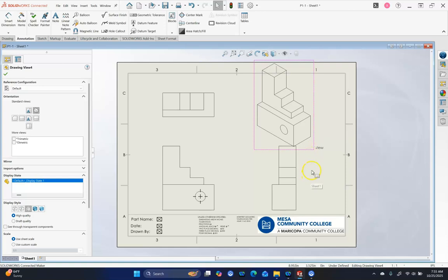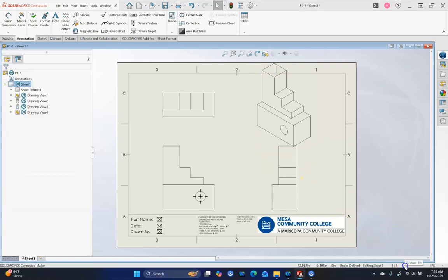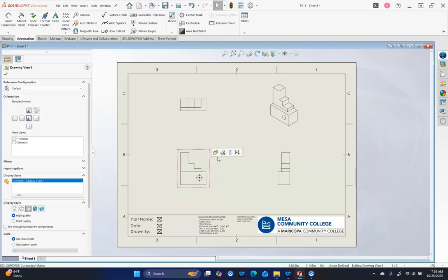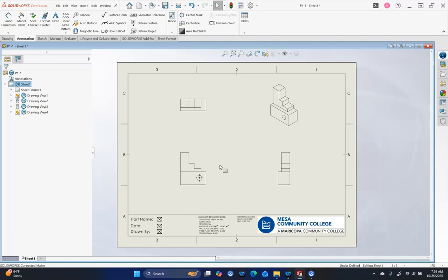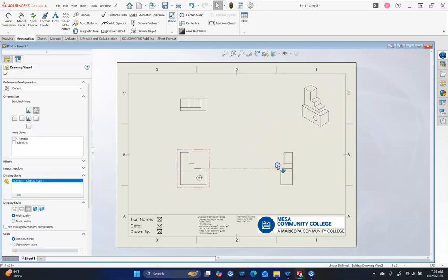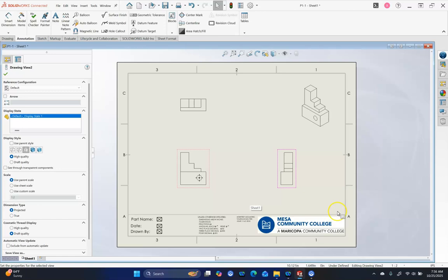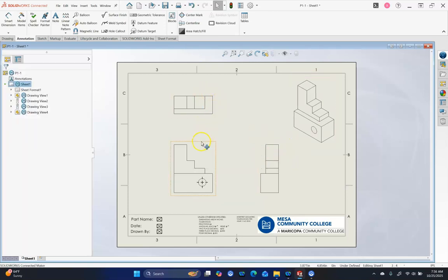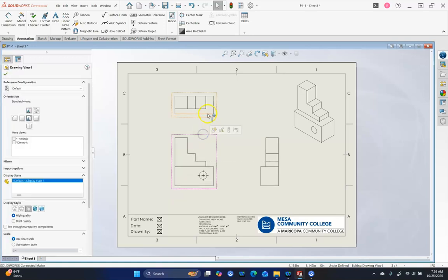All right, so to make the whole sheet a little bit smaller, I don't know that half scale makes it a little bit too small, and this is my A size custom. Just for reference, if this was on a B size, the 1-to-1 would probably be okay. So we can go to a user defined if we want, and I could make this 3/4 scale. All right, and that looks reasonably okay. And we have our sheets in place or started.